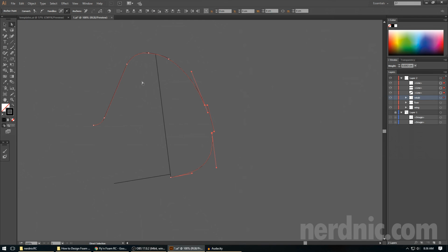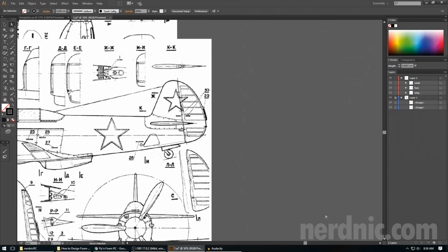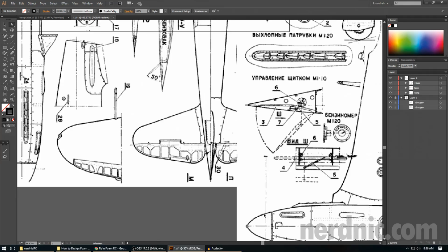And then go ahead and do your selection tool, drag a box around that. And then now what I like to do is select these lines over here with shift. So I click one, hold shift, click the other. It selects everything in between. I can now drag that into vstab. And now I have everything in one piece. Alright, there's that. And now we need to go ahead and do our vertical or horizontal stabilizer.